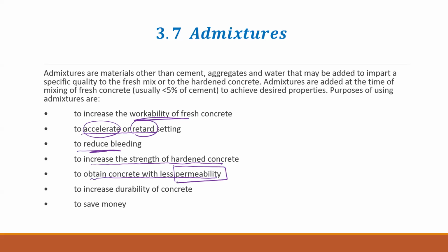In most situations, we need to control the permeability, because permeability is the weakness you have in a concrete, so this will affect the strength.